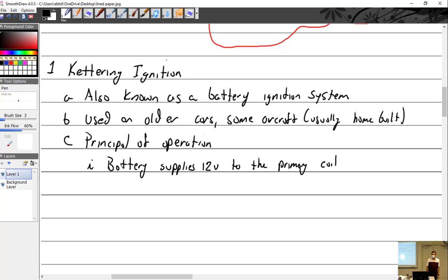If you're doing this at night, the lights are going to get dim. Well, first you're probably going to notice that the speakers aren't working real well. Something's funny with the radio. Then you notice you can't see out the front very well, and it's getting darker than you thought. And that's when you decide to switch it off and back on again to see what happens. And then the whole thing dies.